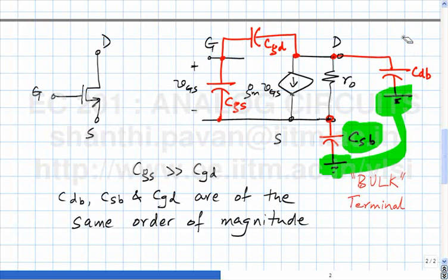The exact nature of the dependence depends on the details of the device operation, just like the formula for GM depends on the formula relating I to VGS. So just like that, the values of these are all incremental capacitances, please note, and the values of these incremental capacitances quite logically depend on the operating point of the device, and the exact relation of these capacitances to the operating point depends on the physics of the device itself.